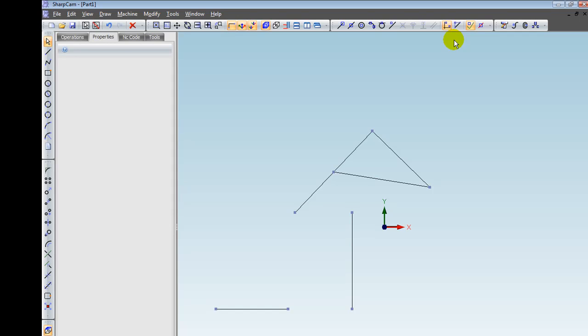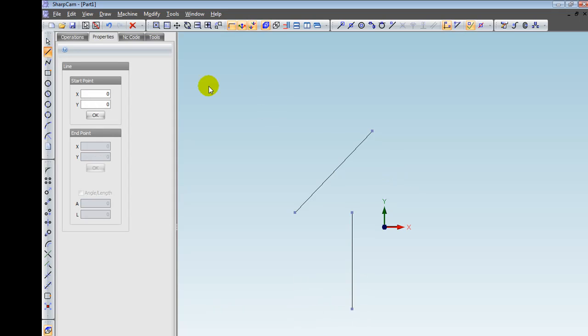So I'm going to show you intersection snapper now. So I'm just going to delete a couple of these lines now. So delete, and then just draw a line that intersects that line there. So again, snapping will look for intersection points, and there we go, it's found the intersection points of those two lines, and they've both been highlighted to indicate that.